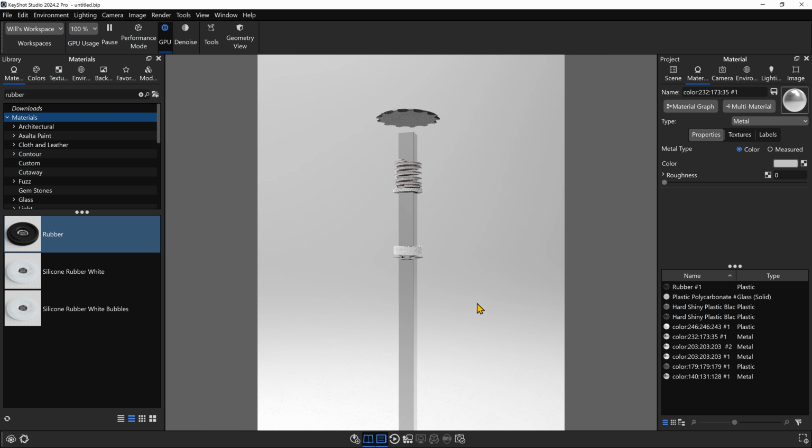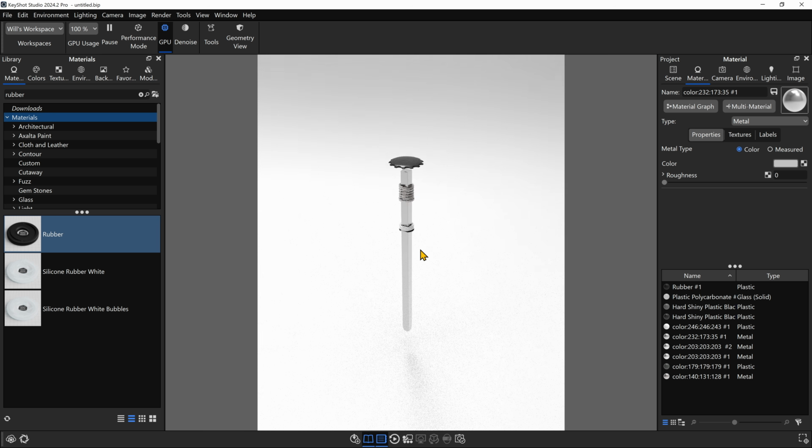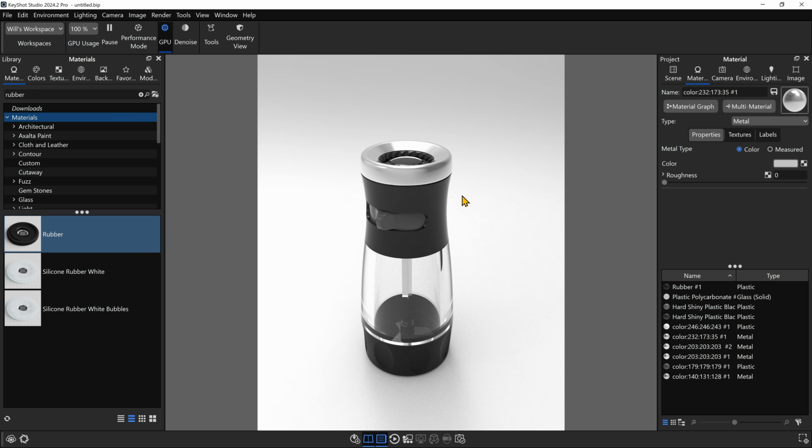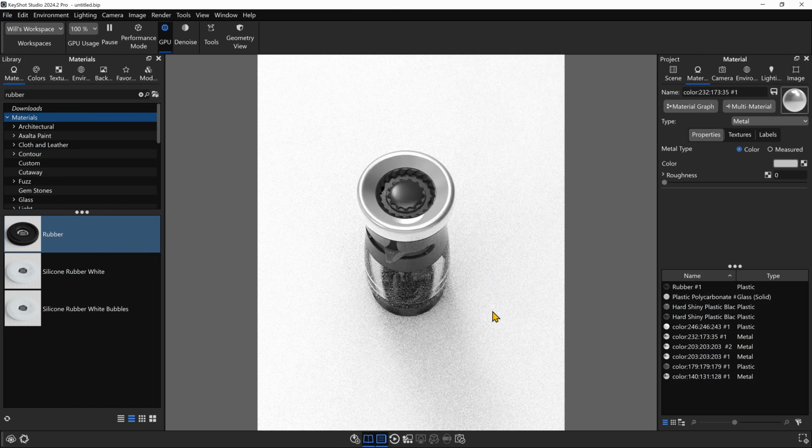So now we've basically made sure that all of our parts in our entire scene have realistic materials. And we can see that because in our scene material list, we don't see any more diffuse materials. Now to bring everything back that we've hidden, we right click and show all parts, and now they come back into view.